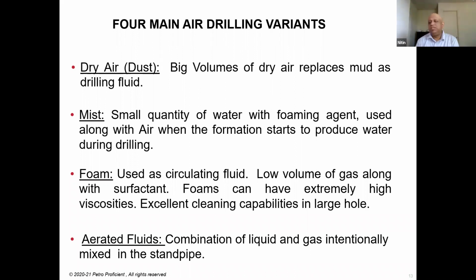Now, what is mist drilling? What happens is when small quantities of water are produced by the formation while you're drilling, a small quantity of water is added along with a foaming agent to the air to ensure that the produced water is lifted.